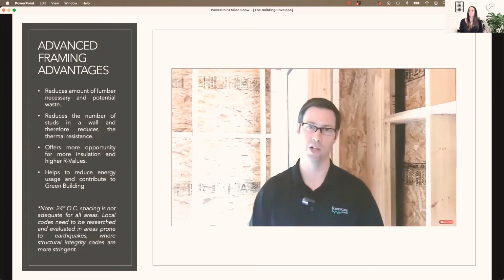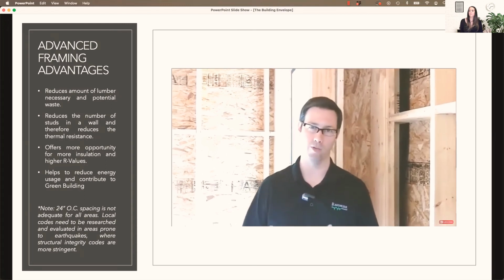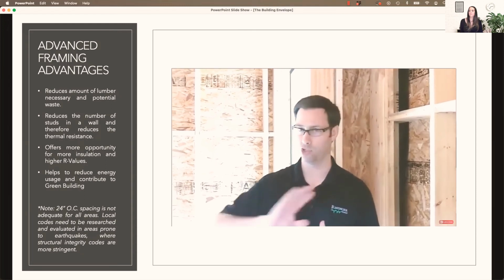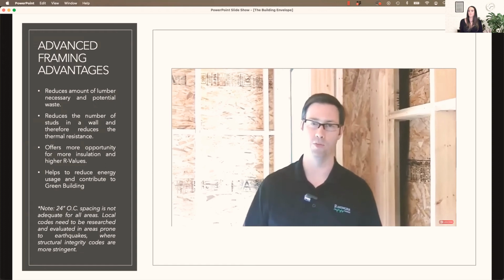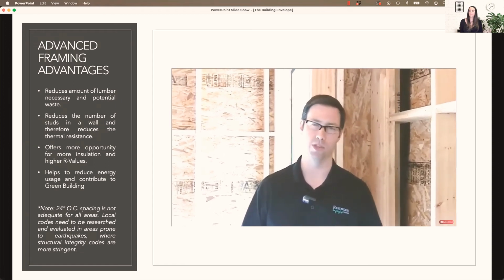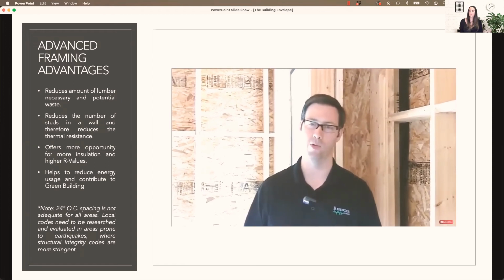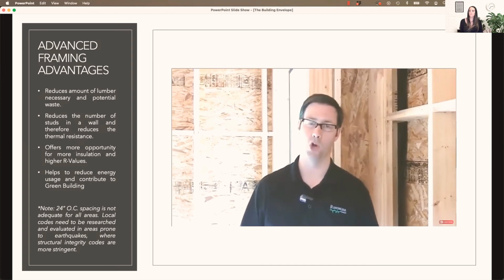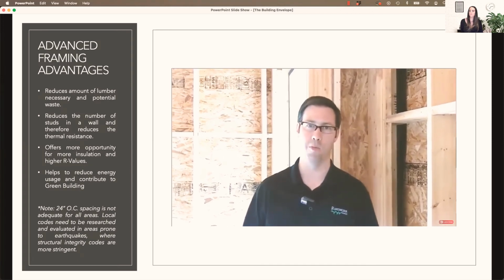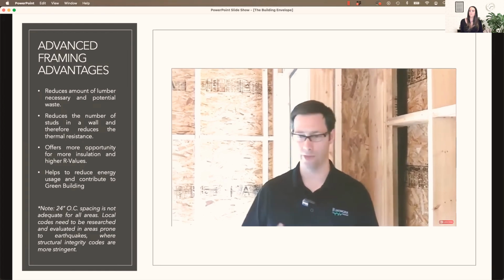We're not using texture. And that 5/8 rock, sheet rock, is much stiffer, gives a much straighter wall, and looks better in the finished product. And when we're going to 24-inch centers, I think that really makes sense to use that 5/8 sheet rock. It also ends up with a little bit of a quieter house because we've got a little bit more mass in our wall cavities. I think that's about it.